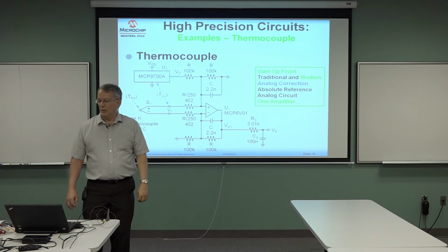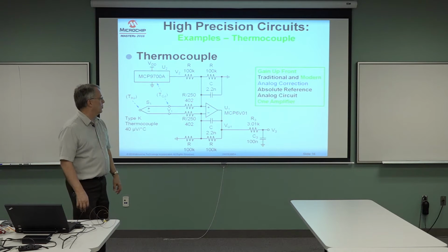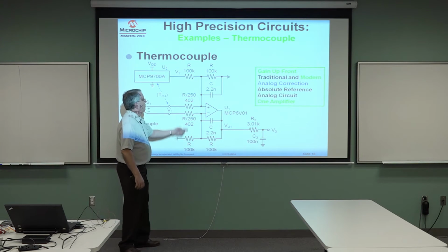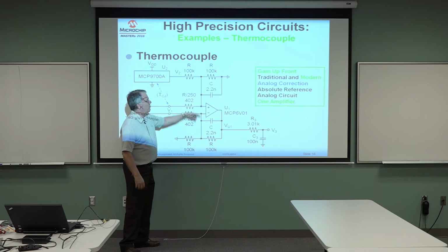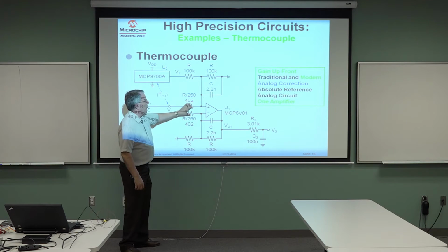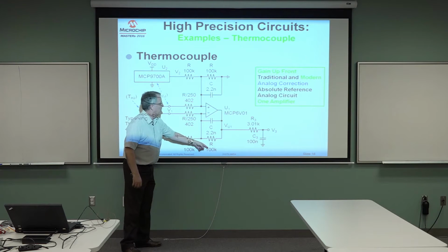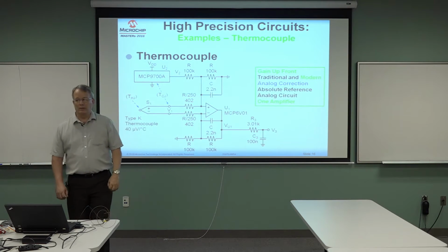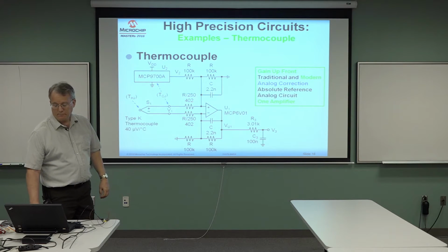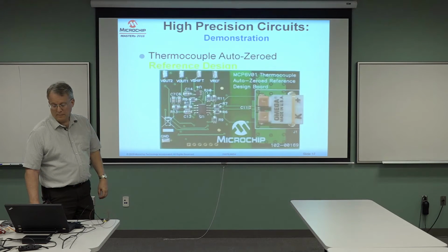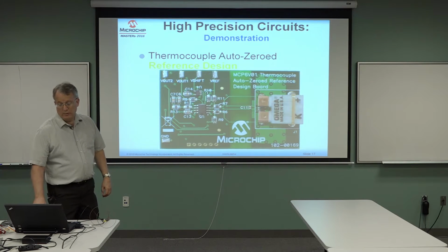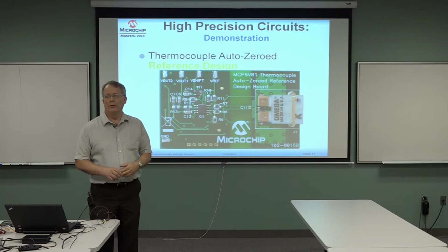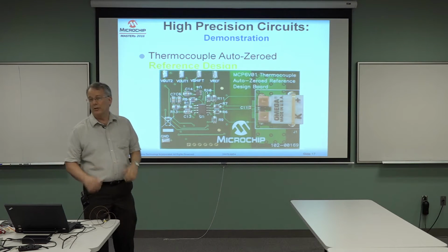Just as a comment, not everyone may be aware of this, but with this circuit, you can put multiple differential inputs into this difference amplifier by just putting 2 more resistors, and it's just simply the ratio of these resistors that sets the gain for each individual leg. It's not more complicated than that. So we've kind of gone through a few circuits fairly quick. They've shown the more modern approach where we try to reduce the number of amplifiers.